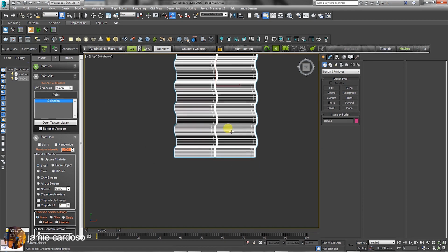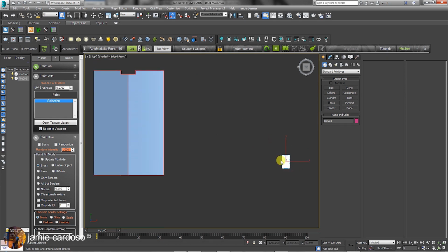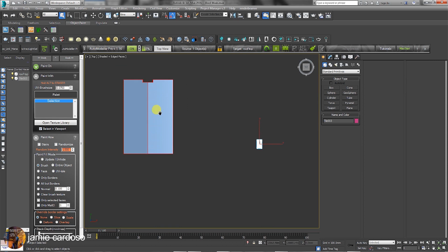When modeling objects to be later painted onto objects, ensure to start modeling them from the top viewport. This is to avoid any potential problems down the line. To set this roof tile mesh as a source, make sure the top viewport is enabled. While the roof tile mesh is selected, click on the Sources button here. Before painting, you can choose the view to paint from here.